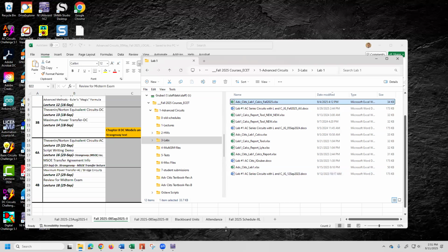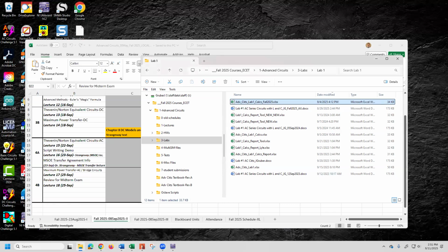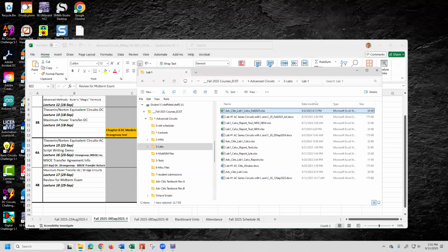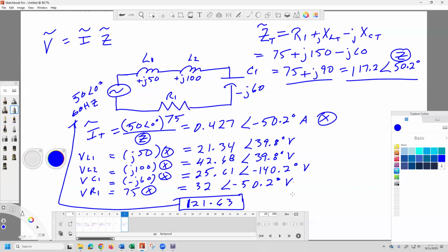Where you add the voltage, not the angle. Yeah, the whole point was just to show that it doesn't equal 50. I think I got 120 or something like that. Here, I'll do it again. Don't add the angles, add the magnitudes. What does it say? It says add the magnitudes of all the voltages.